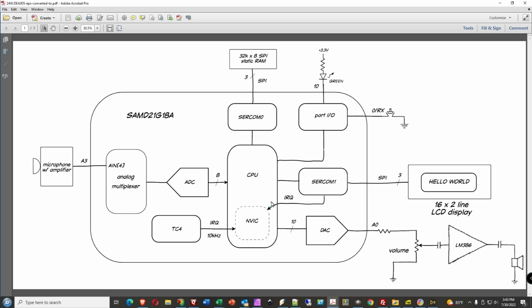Meanwhile, the foreground program monitors the button. If during playback the button is pressed, it resets the count of bytes to play back in the timer counter interrupt to 0, which effectively says there is no longer any recording, and that stops playback.